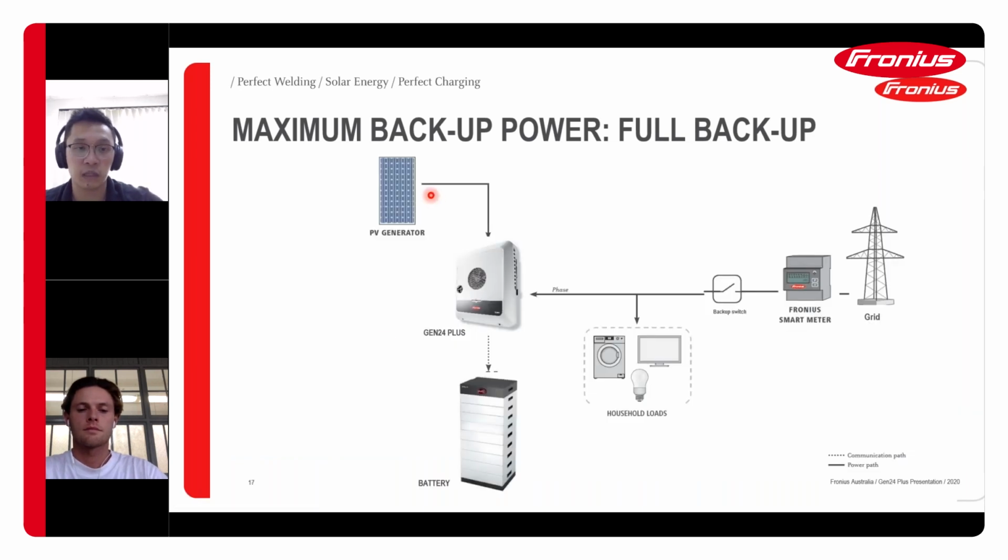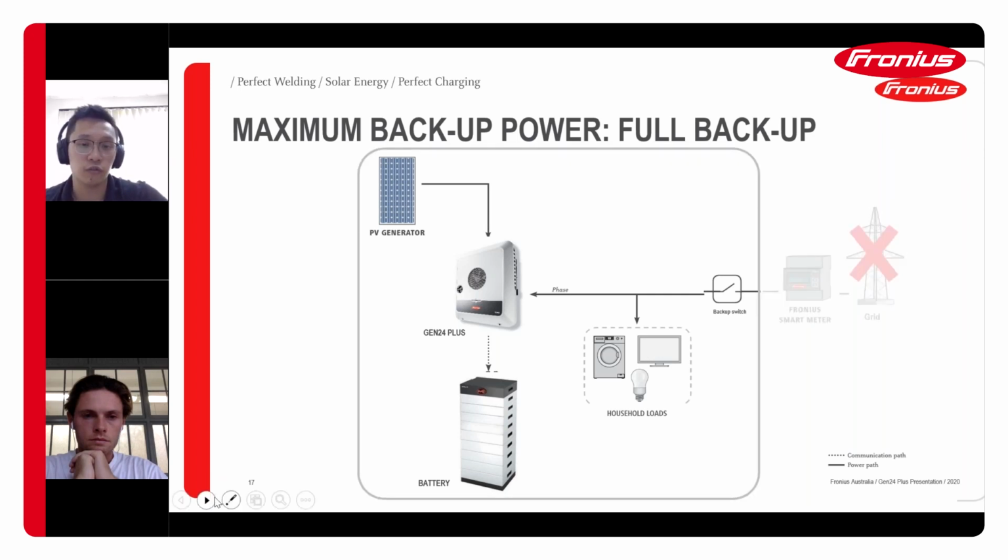So in this particular full backup, what you will need then is a backup switch. That's where you need to do a bit of rewiring, and we have a recommendation of what to use there. So here the grid goes down, your backup switch opens, and you go into this full backup mode.